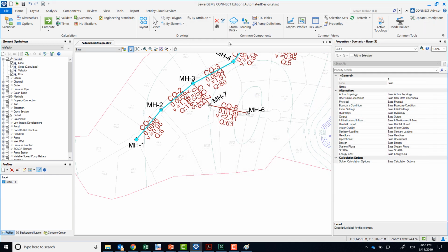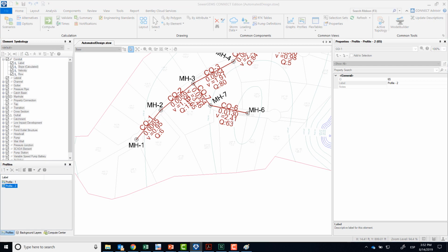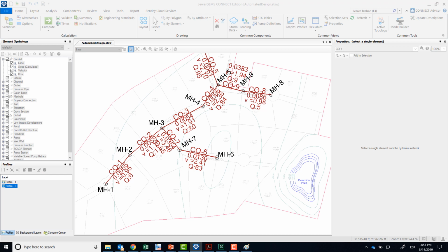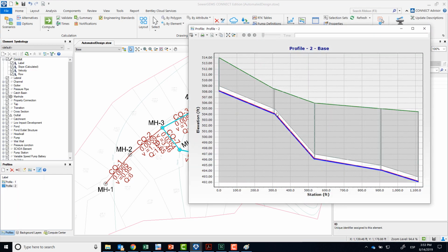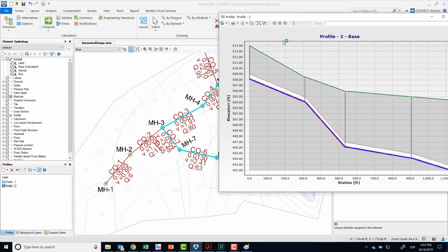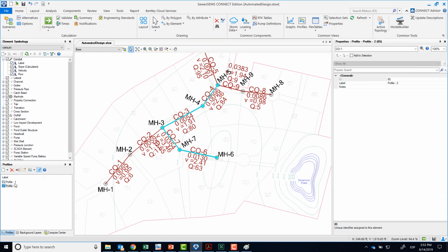So that could have been improved. If I also did a profile, just so we're aware, from here, let's do it all the way to here. I'm going to show you. This is manhole 6. So we're going to keep an eye on both profiles. So again, this is what we're seeing here, that 0.003 slope. Okay, so that's where we started.